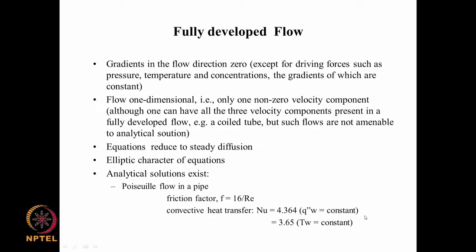Another assumption that we often make in order to get some insight into fluid flow is the fully developed flow assumption. So, except for driving forces such as pressure, temperature and concentrations, we say that the gradients in the flow direction of other quantities are 0, and the gradients of these quantities are constant. Okay. So, we reduce the problem to one-dimensional flow, and you have only one non-zero velocity component, and you have an elliptic character of the equation, we will come back to that,